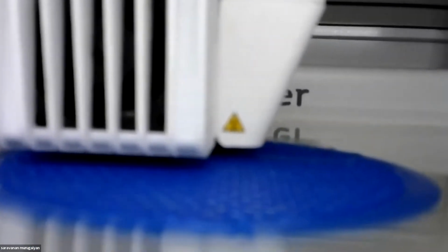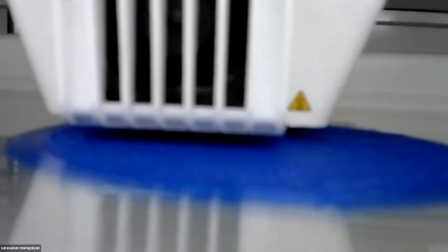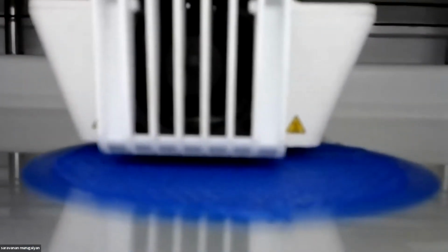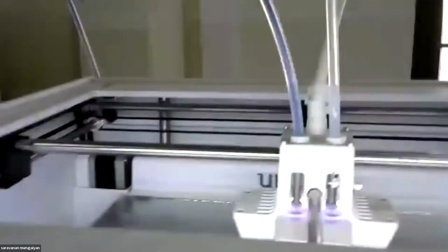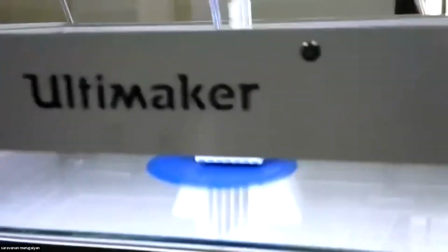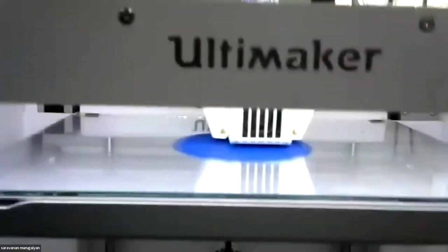The nozzle diameter of the printer is around 0.8 mm. So the maximum layer thickness that we can achieve with the printer is around 0.8 mm. Each and every layer that we print is uniformly maintained in the range of 0.1 to 0.5 mm usually, and we can also go below 0.1 mm in certain cases. And speaking about the construction of the machine,